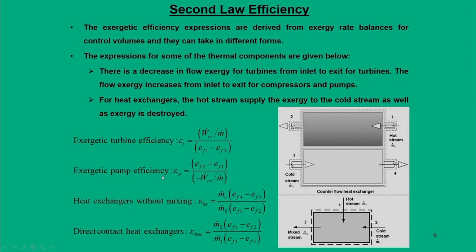Similarly, for the pump case, work is input to the system, so it is in the denominator with a negative sign, and the exergy in this case increases. So there is a decrease in the flow exergy for the turbine from inlet to exit, and there is an increase in the flow exergy from inlet to exit for compressors and pumps. Another very vital part is the exergy calculation for the heat exchanger.